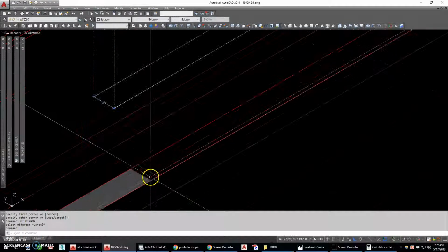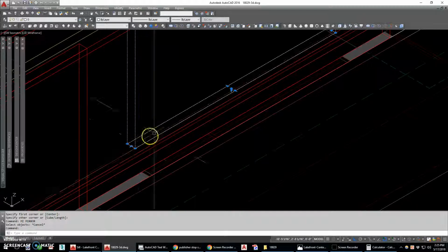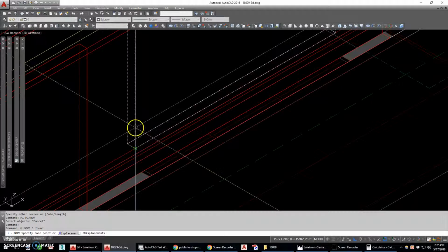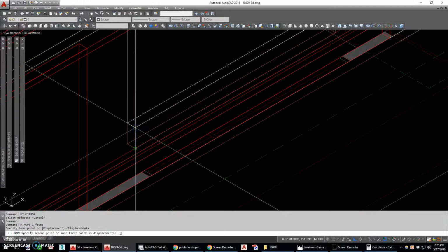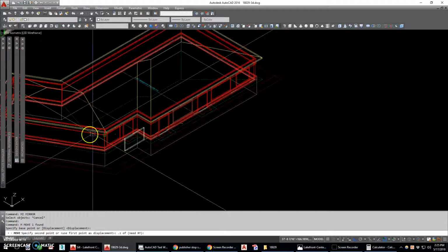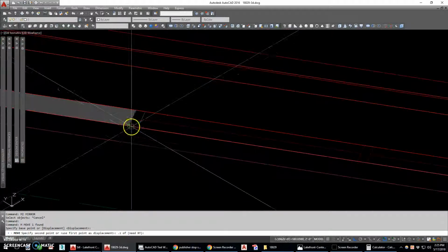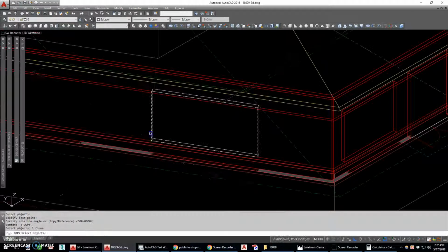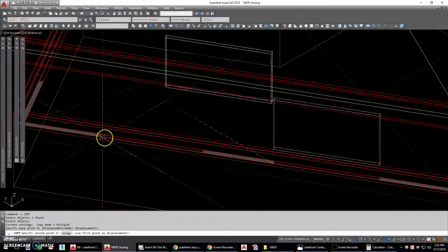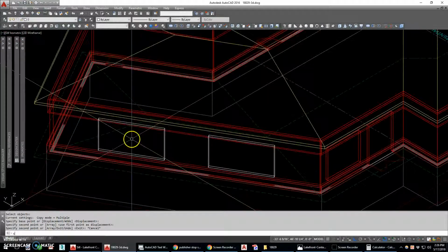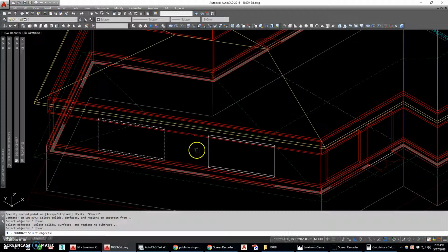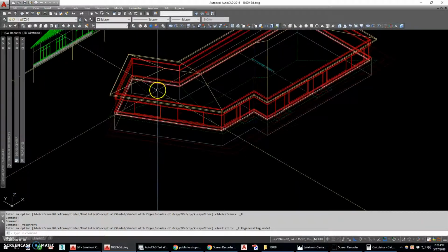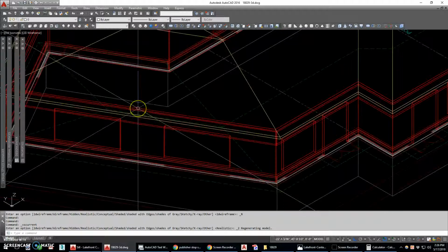and move that box. See, it doesn't look like the elevations line up exactly with the floor plans in this case. So what I'm going to do is move this box from this point to the Z point of here. But I'm going to pick my new XY as this corner. Now I ought to be able to rotate this into place, copy it relative to the plan. And if this works, I should be able to see through my building. Yep, got some window openings. So that looks like all we need for now.